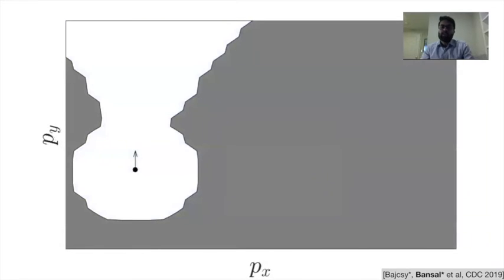Now, when nothing is known about the environment, we treat everything that the robot does not know about as an obstacle. So we assume everything in this gray area is an obstacle. Obviously, that seems like a crazy idea, at least, because our goal now is an obstacle. But you will soon see that this allows us to provide safety guarantees in the environment, and also we will refine this gray area as the robot is moving in the environment.